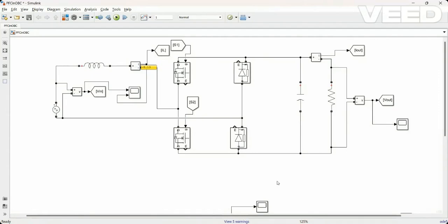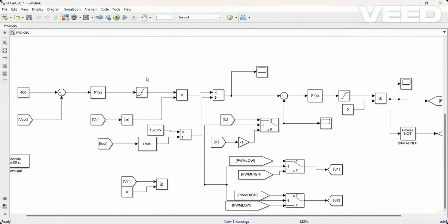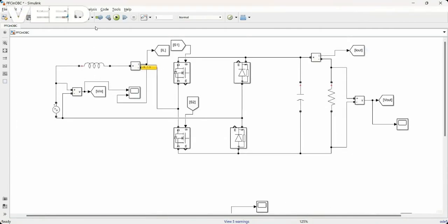All right then, it's time to look at the results of our logic. I have basically tuned some of the P and I, proportional and integral, constants. It's at 10 at the moment, but you can also use the Simulink tuner app. I'm not sure, we can give it a try later on, but we can have a look after simulation. Right now it is simulating, and this is our scope.